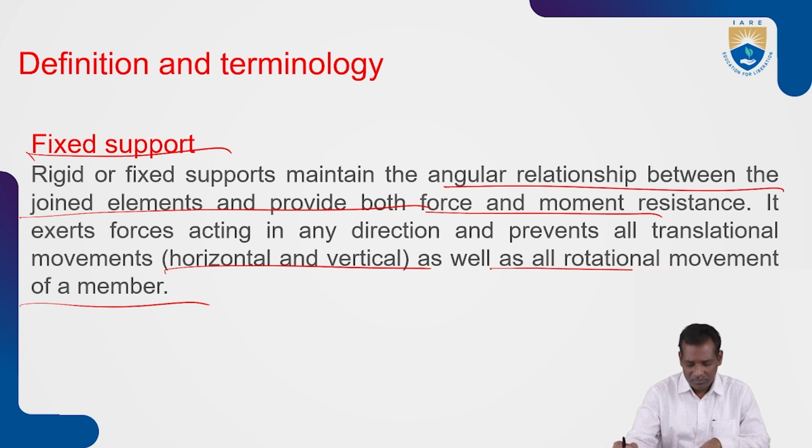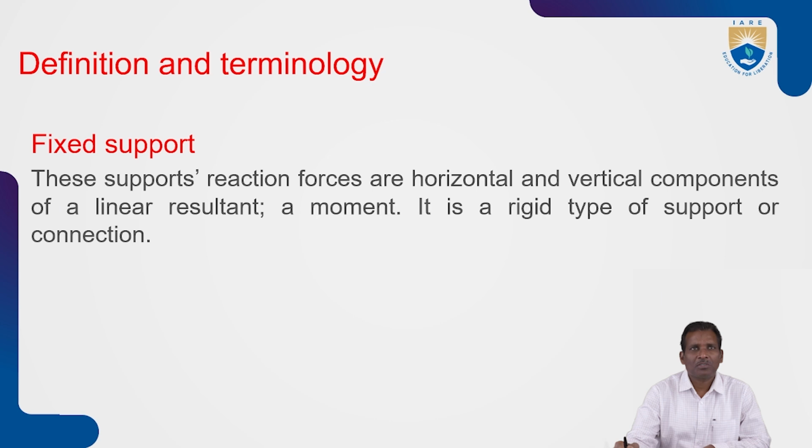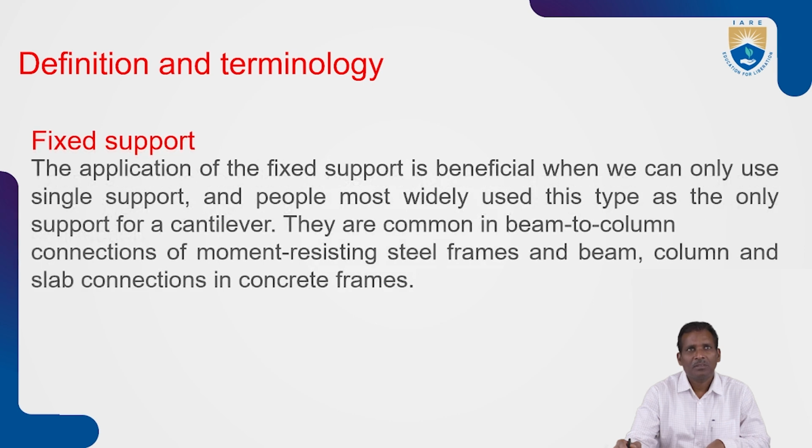See fixed support. These supports' reaction forces are horizontal and vertical components of a linear resultant. It is a rigid type of support. The fixed support application is beneficial when we can only use a single support. People widely use this type of joint support as the only support for a cantilever beam.